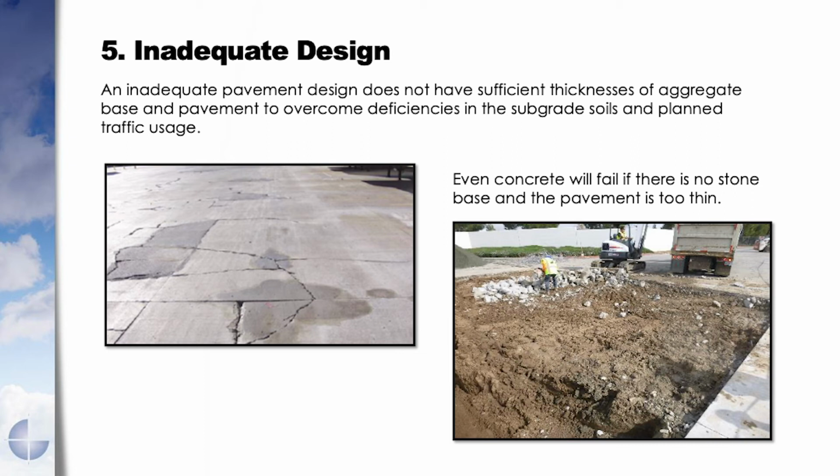The photo on the right is another project. This was a concrete parking lot just for light cars and trucks, but it failed prematurely. Again, within 10 years, when concretes are expected to last at least 20 years. Well, once the concrete was removed, it was found that there was no stone base underneath it. As you can see, it's just the native clays. It looks a little moist, so it wasn't real solid.